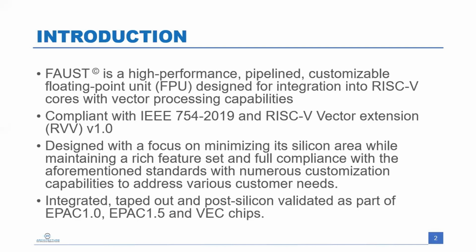It has, I would say, 2 major advantages. First of all, it's compliant with IEEE 754-2019, which is the newest standard regarding floating point computations, and it covers, of course, the RISC-V 1.0 vector extensions. We specifically optimized it as much as possible so that the actual design can be as beneficial as possible for our vector unit.